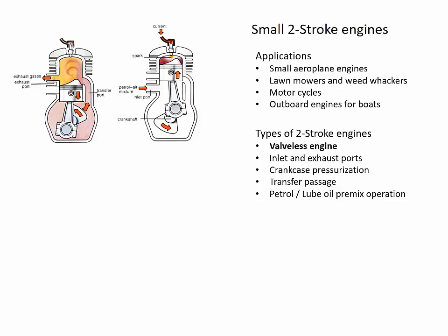Within the design of the two-stroke, the original design had no valves, so we would call that a valveless engine for our purpose. However, to get air in and exhaust gases out, we need ports for this, and the inlet and exhaust ports can be seen in the diagram. So the inlet ports are on the lower end of the cylinder liner, and the exhaust ports are above the inlet ports on the cylinder liner.